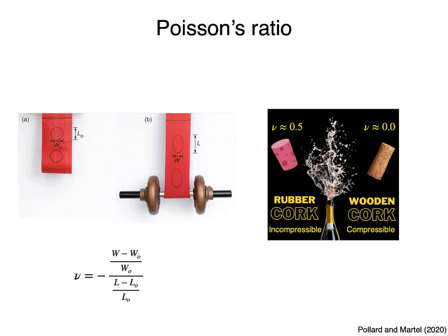The possible values of the Poisson's ratio are between 0 and 0.5. Rubber has a Poisson's ratio of about 0.5. It is nearly incompressible and maintains a constant volume by laterally expanding just enough to compensate for a given shortening. Cork has a Poisson's ratio of about 0. It is perfectly compressible and can be shortened without much laterally expanding. Therefore, a cork stopper can be cylindrical, while a rubber stopper must be tapered.